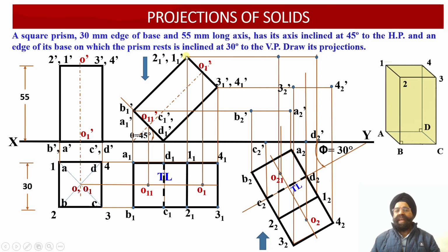And next we have got points 2,1 dash and 1,1 dash. If we draw a horizontal projector line through 2,1 dash and 1,1 dash, now let us see. Here we have got point 1,2. From 1,2, if we draw a vertical projector line, it intersects with this horizontal projector line drawn through 1,1 dash. So here we obtain the point 1,2 dash over here.